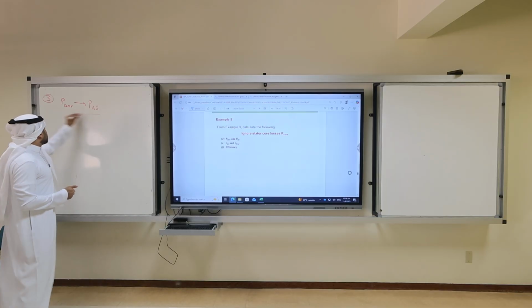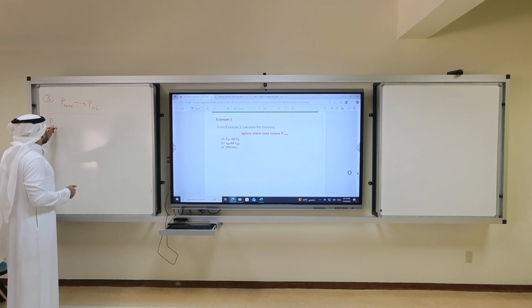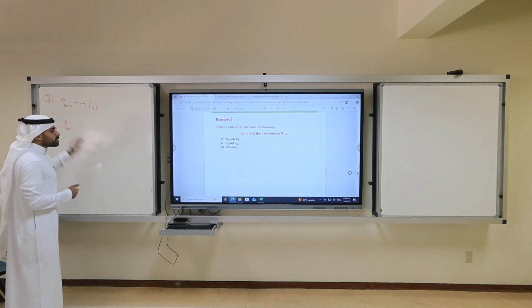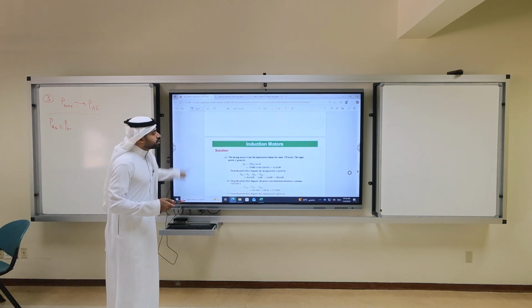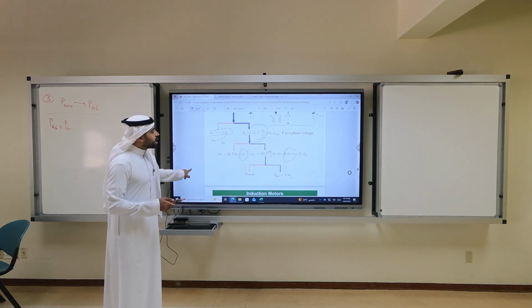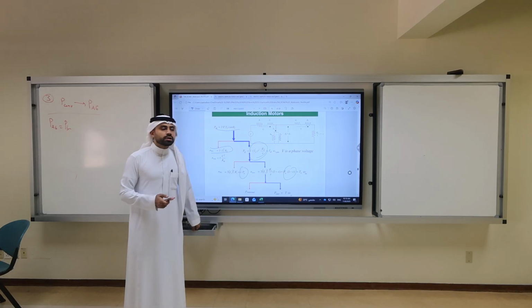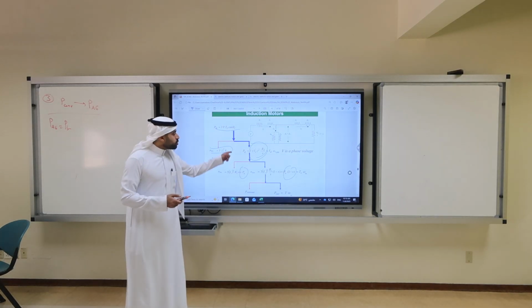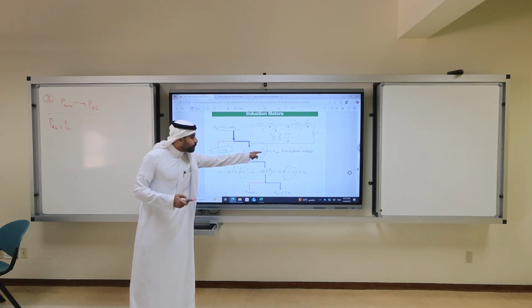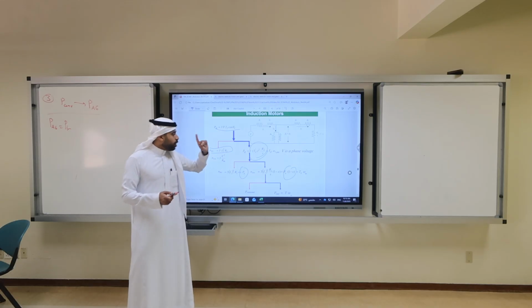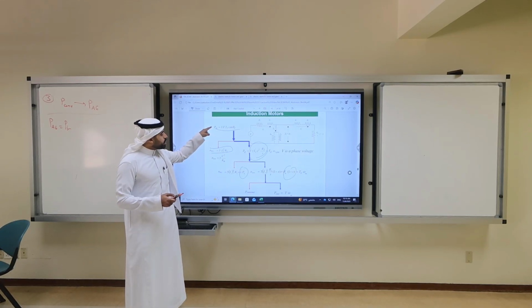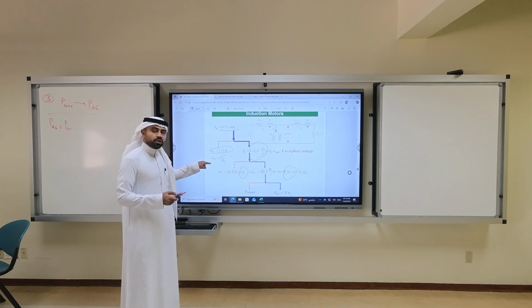But what is the air gap? The air gap is the input power. Go to the equation. In example 3, did I calculate I1 or I2? I1. So do not calculate the air gap from this equation. Your only hope is to get the input power minus the PSL minus the P core.